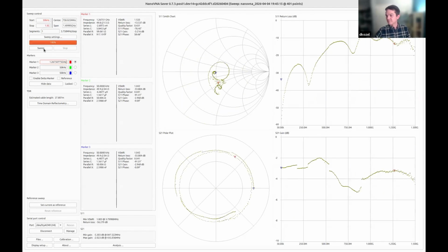Here's a much better plot. This is our 3 dB attenuator connected between both ports. So it's straight through at the moment. Our gain correctly is measuring at -3 dB. NanoVNA again is no prize pony, but we can see out to 500 megahertz or so. That's probably pretty clean. I didn't pay particularly strong attention to how I was handling this.